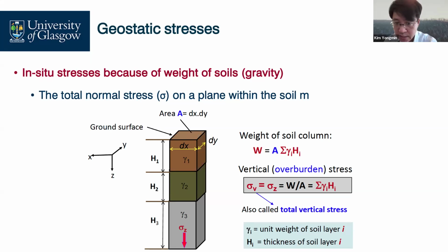This stress distribution is called the geostatic stress condition. Our ground condition is at rest, it doesn't move, right? And then our soil creates certain pressures depending on the soil's unit weight, right? This is the geostatic condition, geostatic stress.